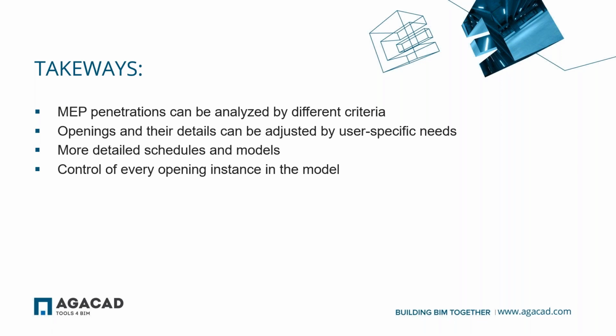Some takeaways. MEP penetrations can be analyzed and controlled by different criteria, and that already depends on the end user, what they want to use. Every opening family can be adjusted, again, to fit company workflow, additional elements added, additional parameters added. With CAD opening, you get more detailed schedules, more detailed models, and of course, control of every opening instance in your model.